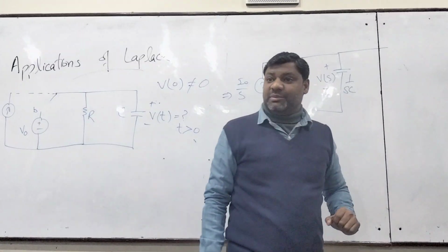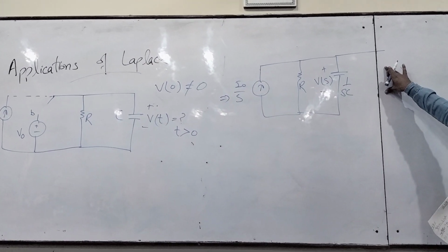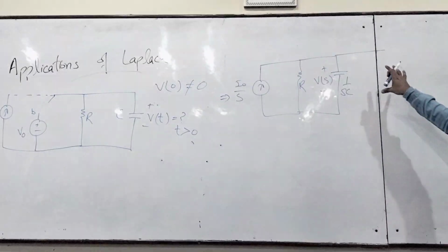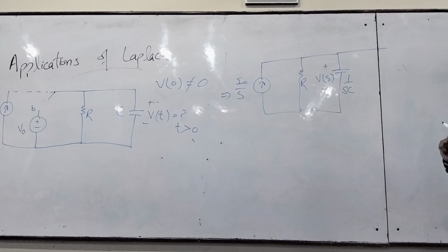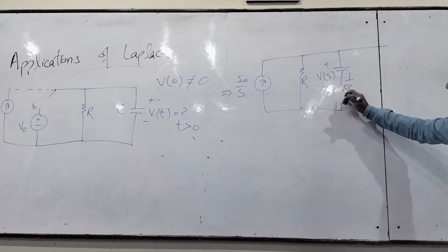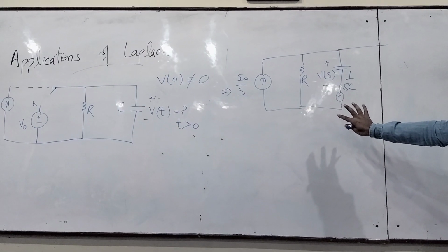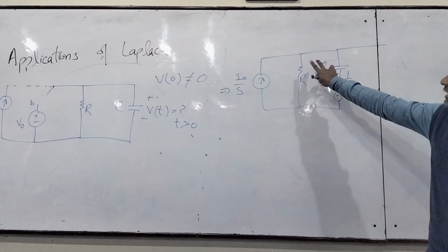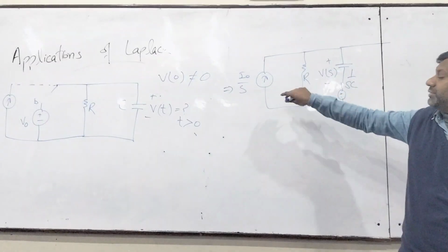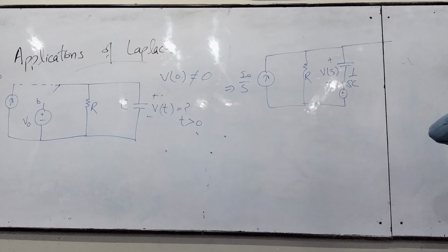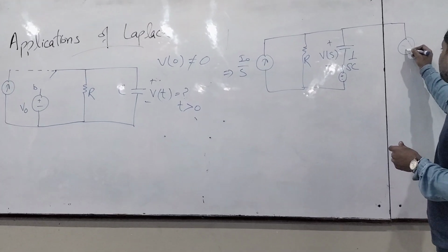Depending upon the structure of the circuit, if we apply a current source here, then we could easily apply the current divider or the node analysis. On the other hand, if we apply a voltage source here, we could again solve that circuit. It's not that we will not be able to solve that, but this time we might have to apply mesh analysis. So you can apply whatever configuration you want. Let me try the current source.